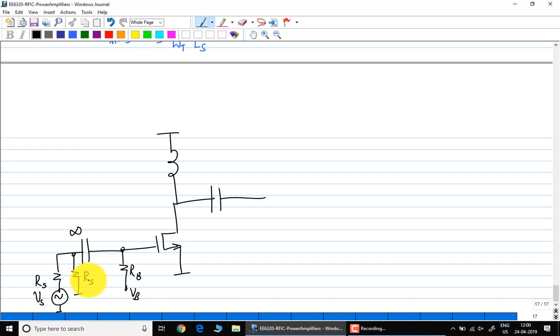I was suggesting something. At the output of the gates, we have the source impedance RS, and we are using RS to terminate it. Yes. Why not use that RS to be a high impedance and match between that and that so that you get higher swing input? You can do this, but the matching network is a lossless network, right? Can the input power ever change? Power doesn't change. Swing changes.